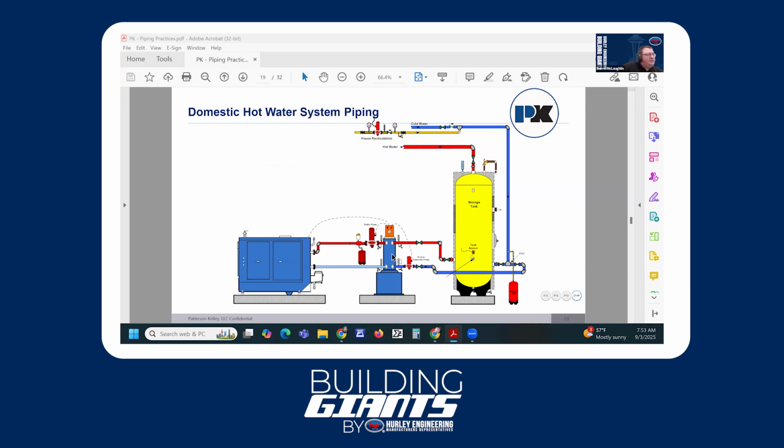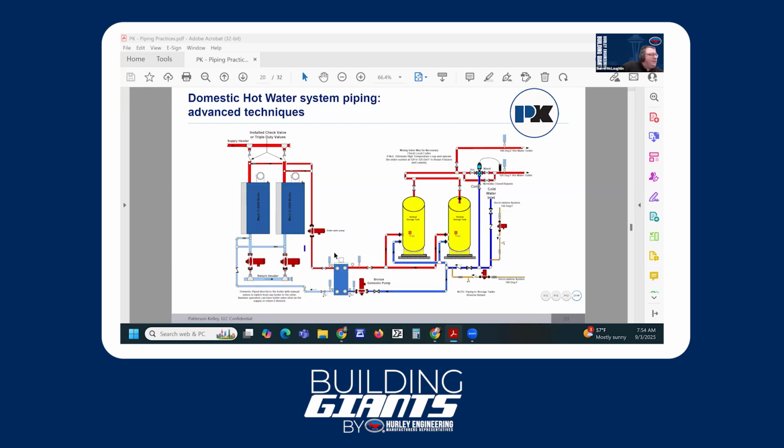Now, if that heat exchanger were to be placed inside this tank, then that would be an indirect heating tank and not a volume storage tank. So in this application, it's an indirect heating application with a volume storage tank. And then the same thing here, we've got an indirect application with two volume storage tanks, and then the necessary piping to keep this all balanced, reverse return, primary, secondary, to keep all our flows consistent.